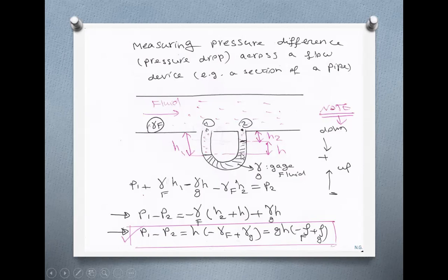One more thing you need to know: for the fluid dynamic pipe, the fluid has motion. So it involves fluid dynamics, but within the U-tube, it involves fluid statics because it has no motion. And that's why you can use this formula, gamma H is equal to P, because the fluid is stationary within the U-tube. Any question?